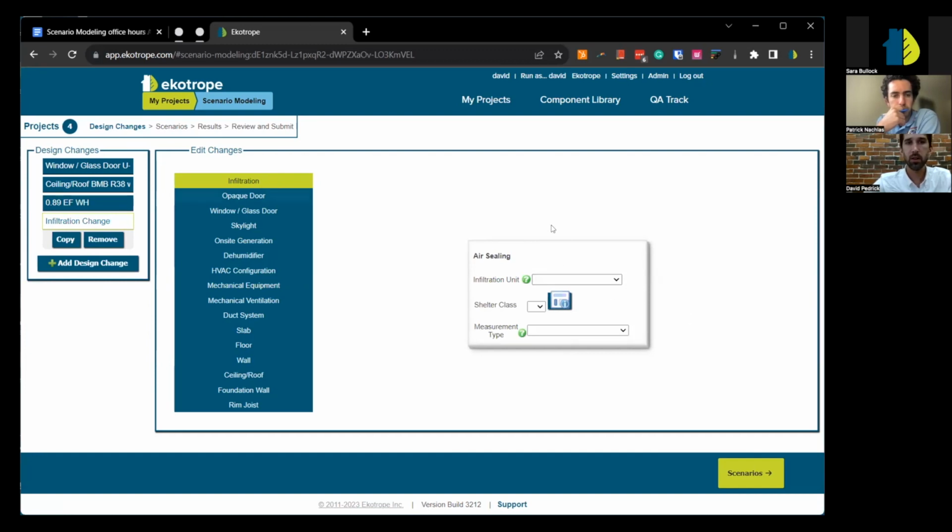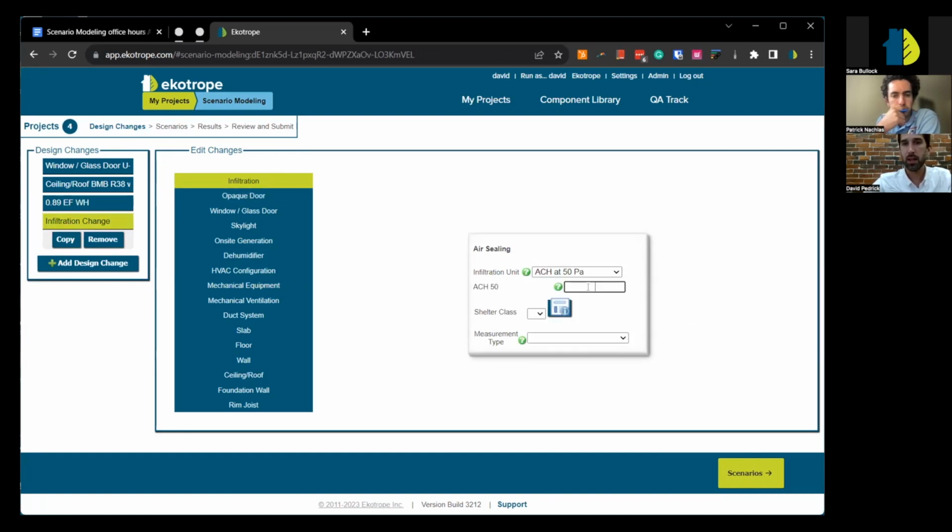So we're going to come over here to infiltration. We're going to say update all of these to 3.5 ACH. And I'm going to rename this as 3.5 ACH 50. And now we've covered all of these situations where the builder called us and said, hey, we can't do this. What will be the impact if I don't do that? And we're going to move on to the next step here.